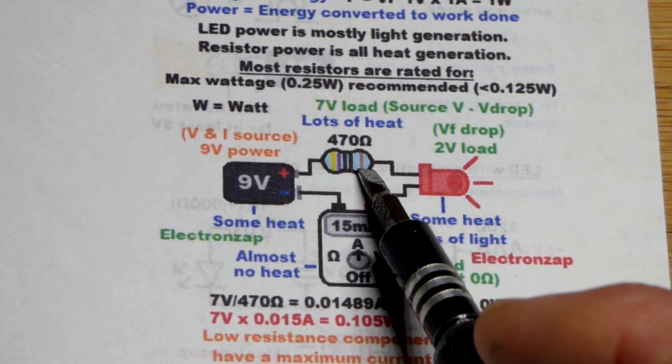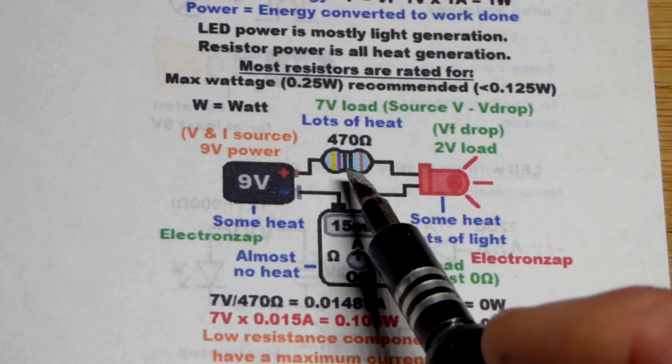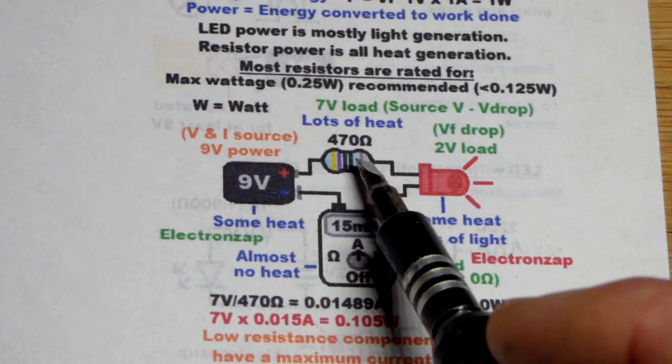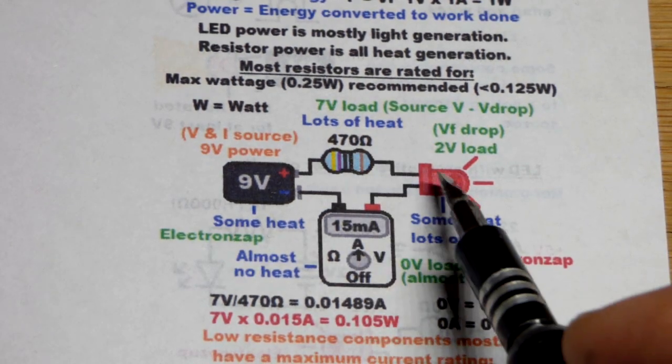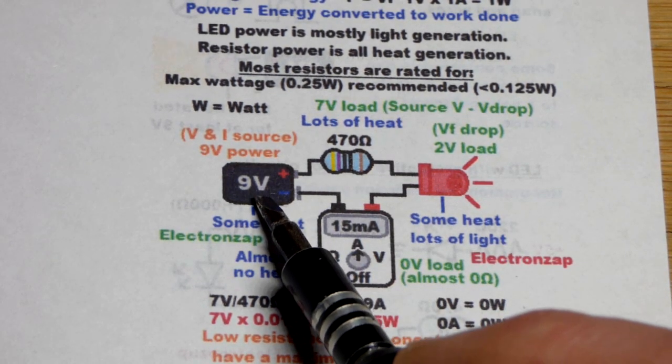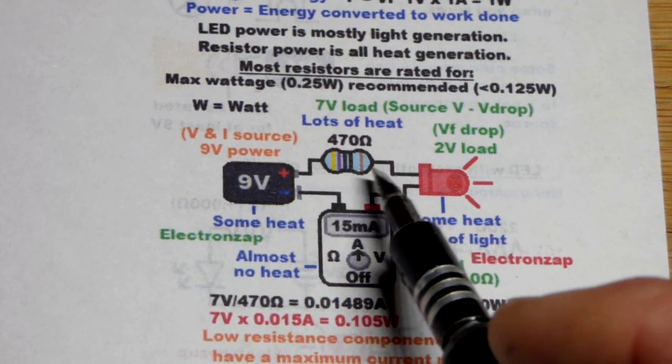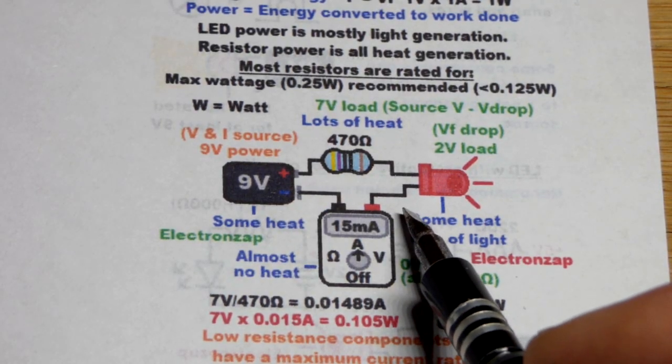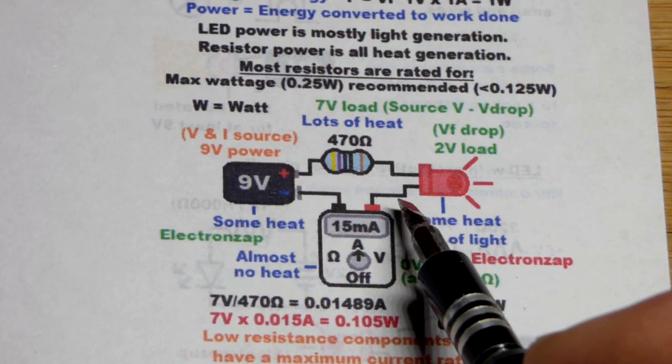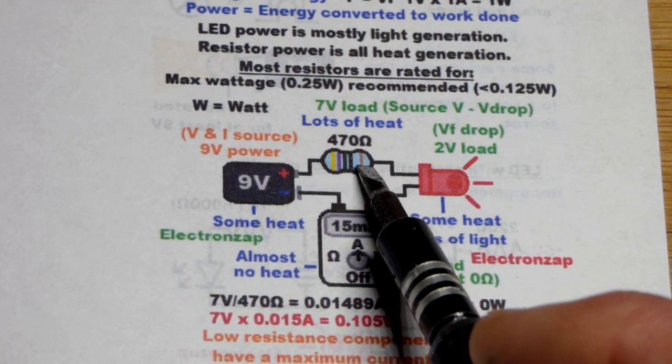And that's why, in this case, we have a resistor. We could also use a current source, something that sets current, so that the current's steady even as the supply voltage changes. That's pretty straightforward. If you learn about current sources, you can apply them wherever. So the resistors are the ones where you really got to do the math and stuff.